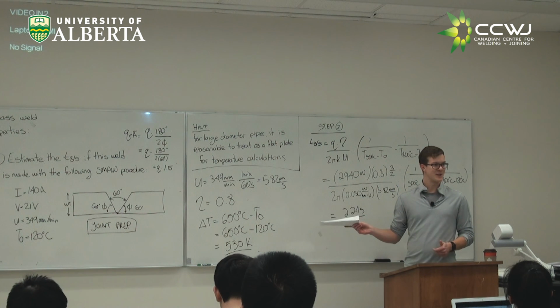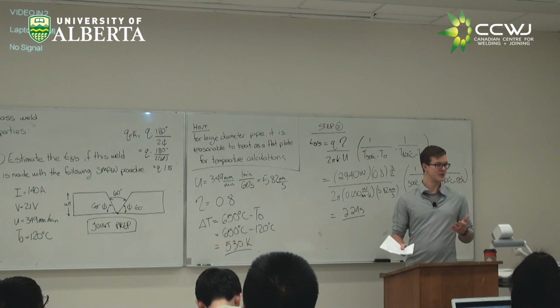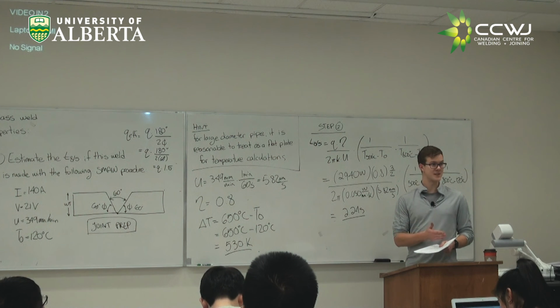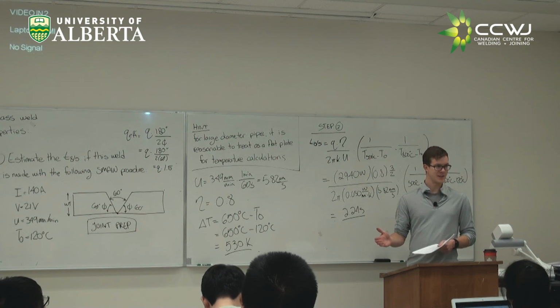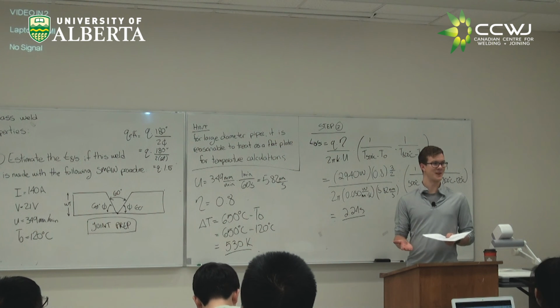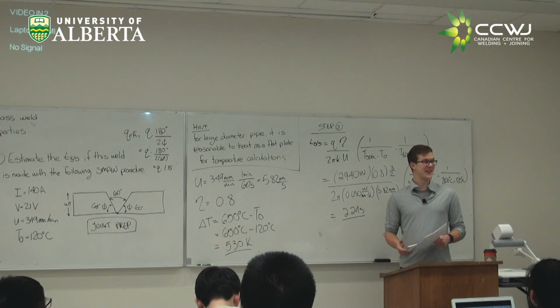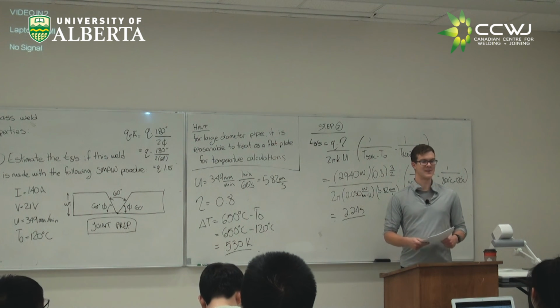If you make a test weld on 11 millimeters, hopefully you now know you can calculate approximately what that's going to give you for a cooling rate. You could use what we did before the second midterm. We can convert a cooling rate to a hardness, right? Question 1 on the midterm: cooling rate, hardness, and you can get an idea for what it's going to give you for the properties of your weld.